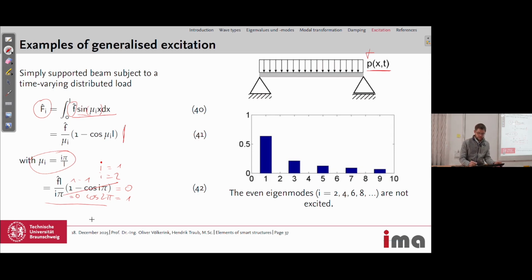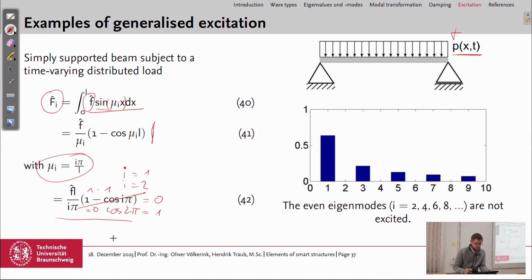So with this distributed excitation of the simply supported beam, we can only excite the odd eigenmodes of the structure.